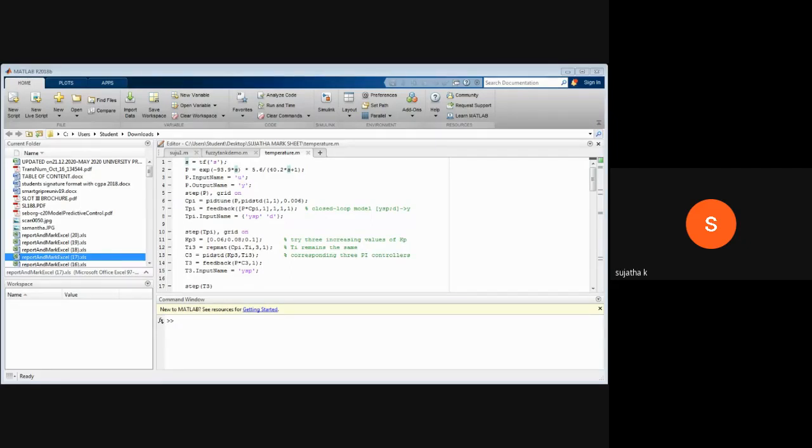So, what I will do is connect this constant block to the summer. And I'm going to change this to negative feedback. So, double click on this. See, you have the sign. Just delete the plus sign and give a minus sign. And give OK so that it becomes a negative feedback.